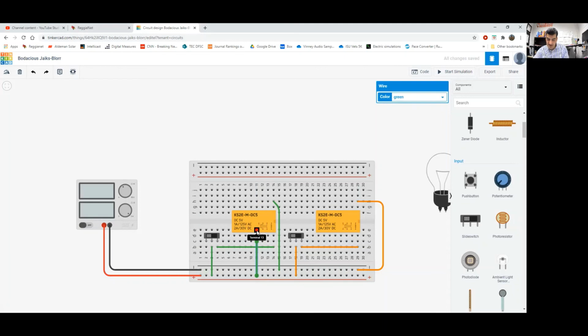And then I need to use CR1A, so I need to use the normally open contact associated with terminal 13, which is this terminal over here, terminal 9. And I need to go from there over to the light bulb. All right, so I'm going to go kind of around, and then I'll go like this, and then down. All right, and now I'll make it look a little better.